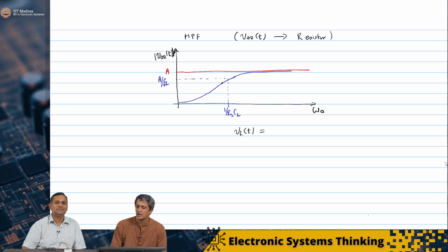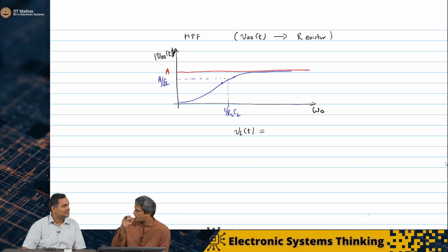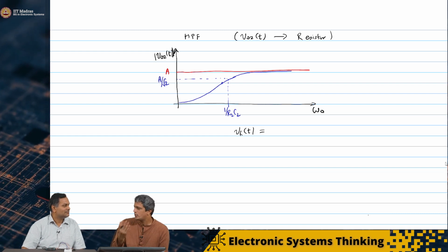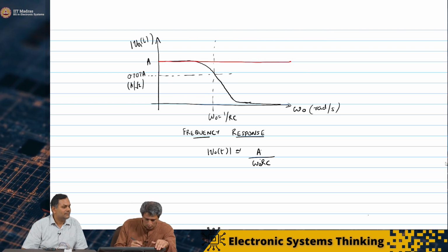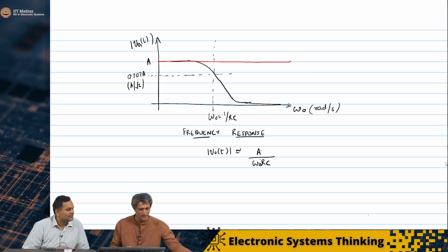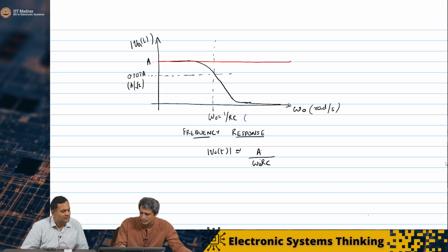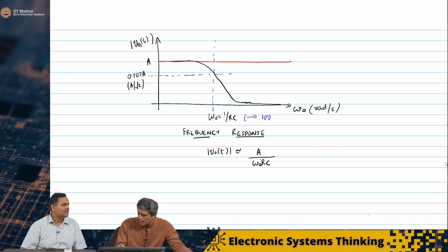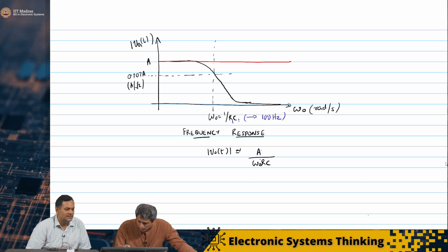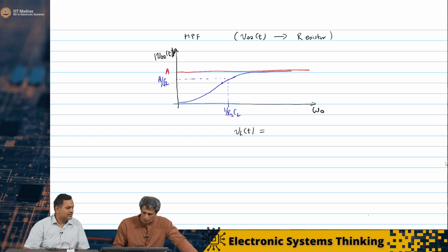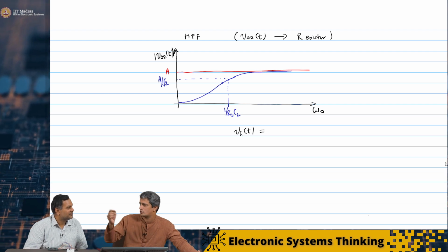Okay, great. Now I want to see how we construct that mid filter. First let's look at how the frequency response of a mid controlling knob should be. What do we want? The low pass filter, if you look at that mixer, was set up to 100 hertz. So this RC will correspond to 100 hertz; we'll just call it R1C1. Or 1 by 2 pi times that, it doesn't matter. And then we said there's another thing which was like 10 kilohertz.